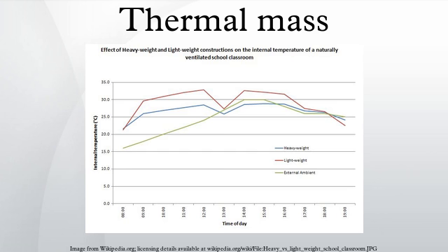If the body consists of a homogeneous material with sufficiently known physical properties, the thermal mass is simply the mass of material present times the specific heat capacity of that material. For bodies made of many materials, the sum of heat capacities for their pure components may be used in the calculation, or in some cases the number may simply be measured for the entire body in question, directly.